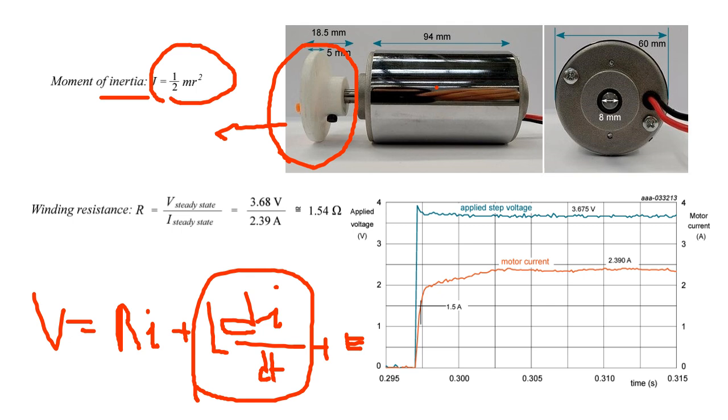Actually, my voltage value will be equal to R times I plus E, the back EMF. So we can say I have some restrictive components, one of them R. So every time, in simulation and in real-time application, we need to measure my R value.